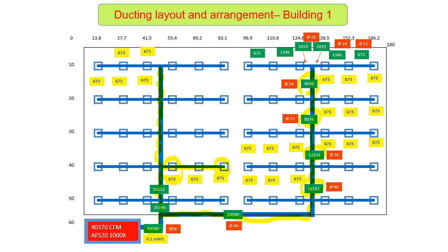After you get the CFM and you get the suitable velocity, it depends on what method you choose, the velocity reduction method or static regain, so whichever, then you will get your CFM and your velocity, and also your static pressure loss, and from here you can plan what is the size for your main duct and also for the branch duct.